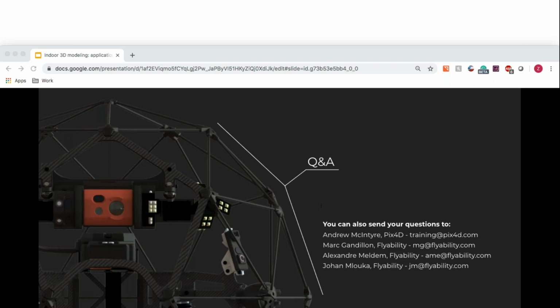But if you are also using those same points as ground control, and you had a known position, not just a known size, but a known location for each of those, then you could use that to georeference. But it is still today a manual process. There is no automatic recognition of the relative scale of those spheres like you have with the point cloud software. That'd be super cool. Yeah, I like the idea.